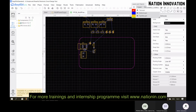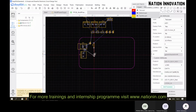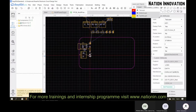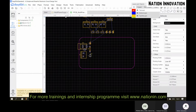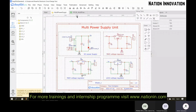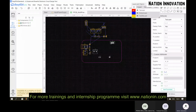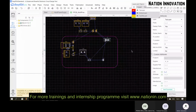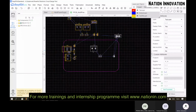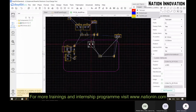Now I need to go for the 7805. Okay. So I will select the 7805. All the components are selected here. I will drag it into my layout. So again, the P2 has to be connected at the border side.